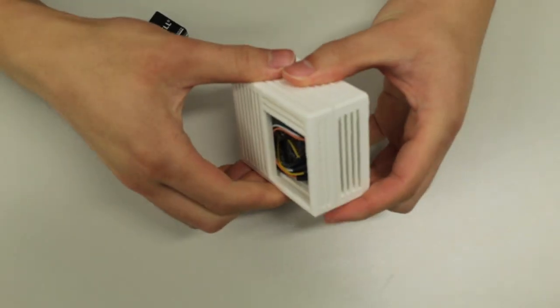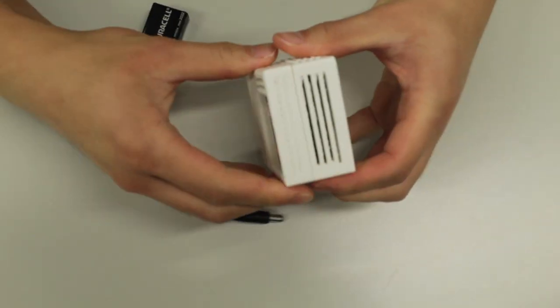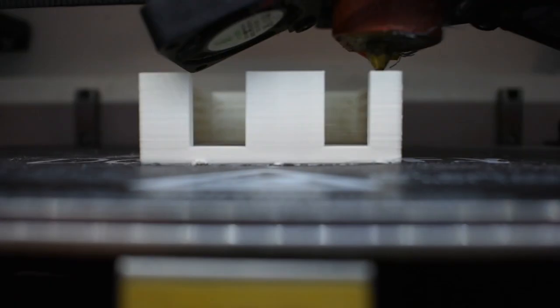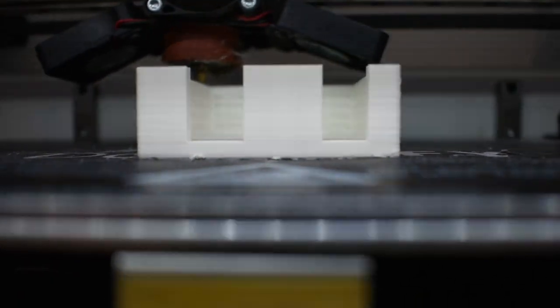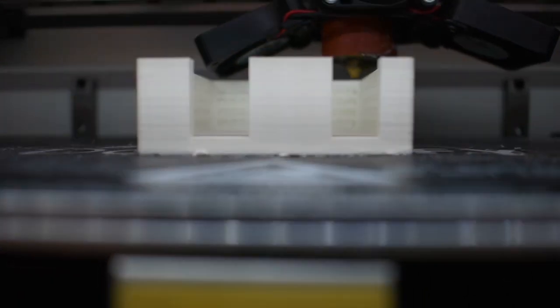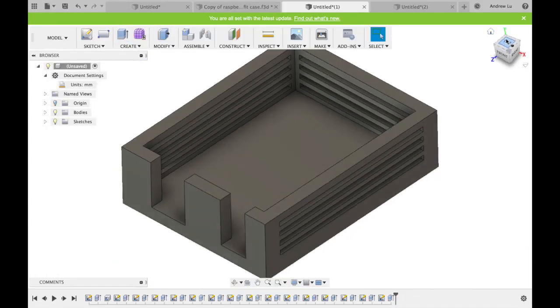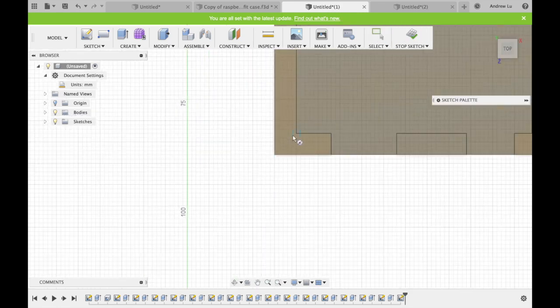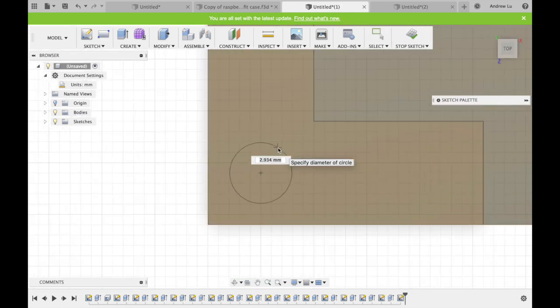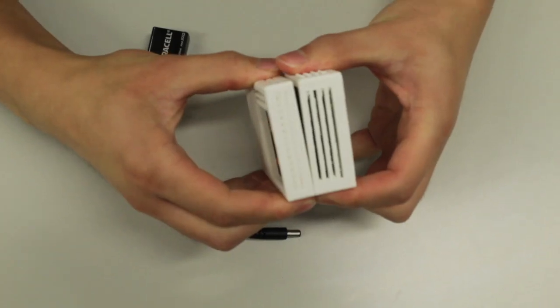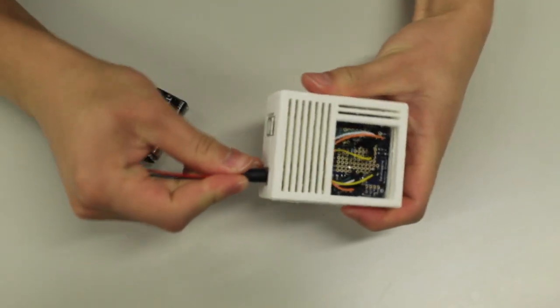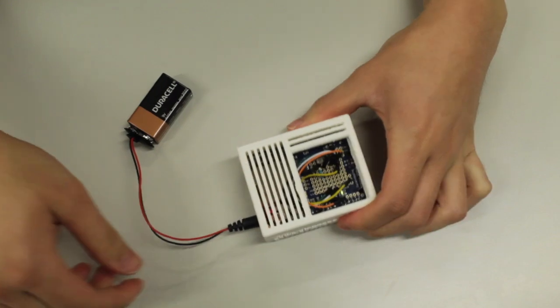First, it was evident that many of the slits on the vertical walls of the case didn't print properly, which can be attributed to the 3D printer's addition of supports during the printing process. Given the size of the supports, it was difficult to remove them, and it was decided that they would just be kept in place to prevent any damage to the sensor case.